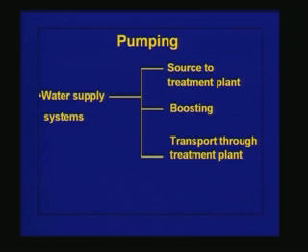In this lecture, we will discuss intake structures and pumping installations, which are an integral part of any water distribution network, or they could be a part of sewerage systems also. The pumping is required in water supply systems to transport water from source to the treatment plant. Source could be at a lower elevation and treatment plant could be at a higher elevation. So, we need to lift the water from a lower elevation to a higher elevation. We need pumping for that.